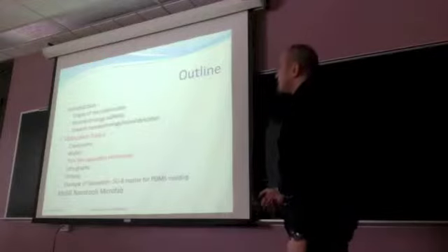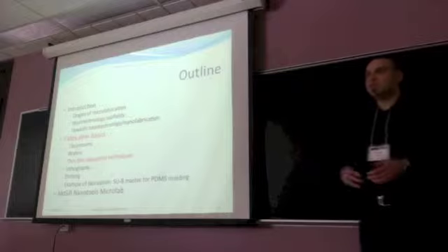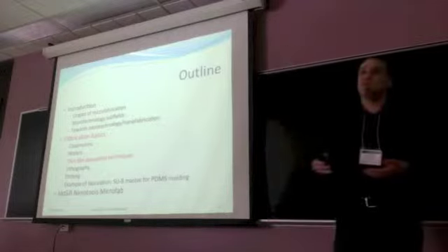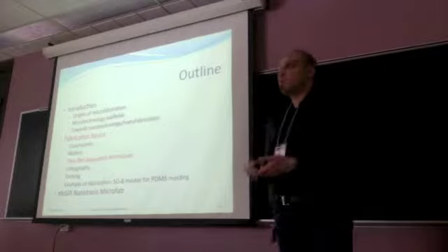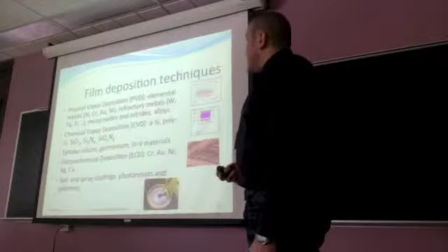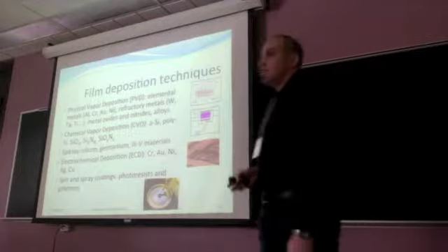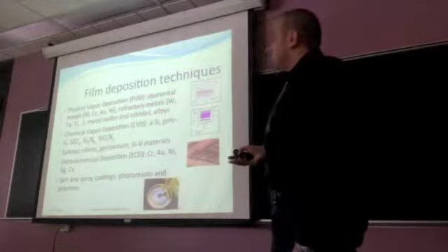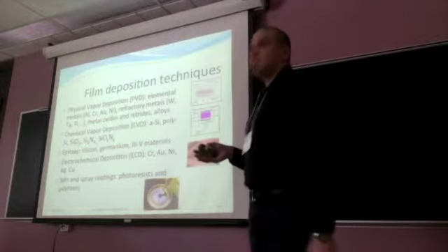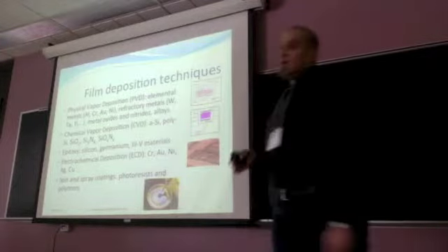So on the wafer, you can use thin film deposition to add more functionality to the wafer, like conduction, transparency, or hard masking. The deposition techniques can be divided into 5 categories. The first one is physical vapor deposition. Physical vapor deposition is based on material ejection. The atoms are ejected in a vacuum from a target to the substrate surface. The ejection can be done by various means.